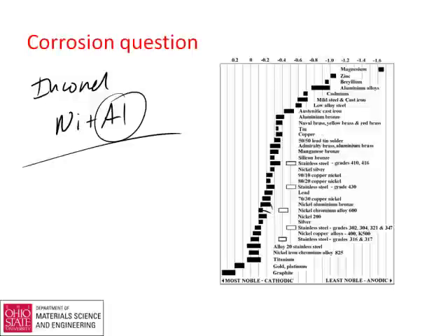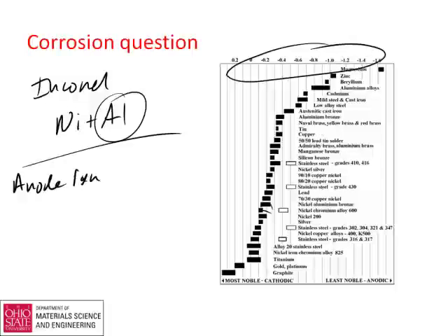So for marine service, you see this is voltage up here. This is corrosion potential in salt water, and basically typically we say if two materials are within 150 millivolts of each other, they're not going to corrode very badly. That probably isn't in the lecture. What is in the lecture is there are two reactions. There's an anode reaction of the type nickel goes to nickel 2+ plus 2 electrons, and that reaction can go on in some regions, and that'll go in the more anodic side.